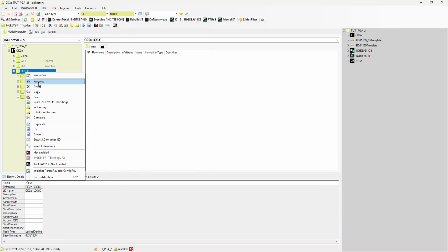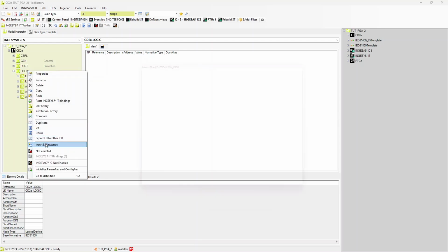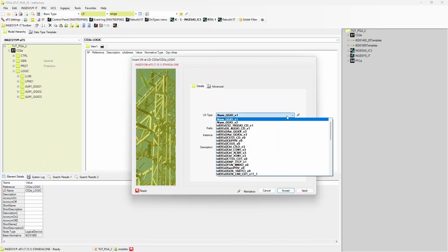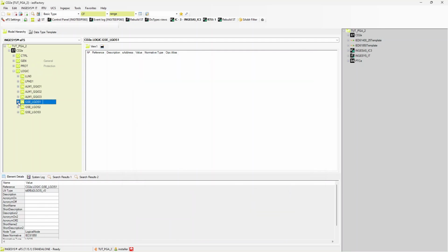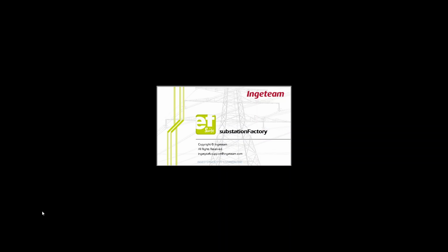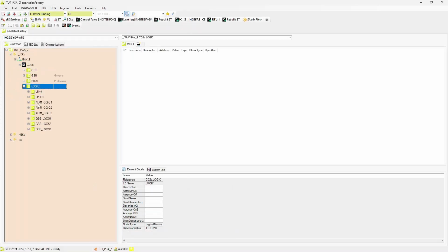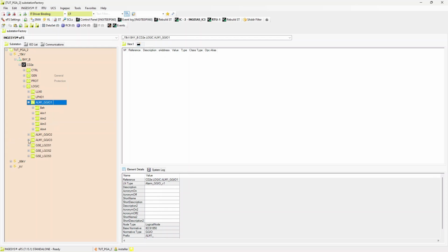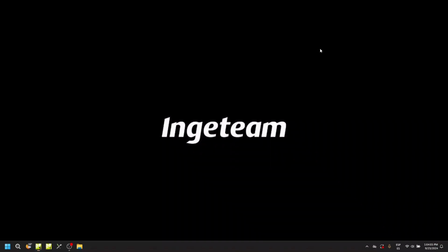Besides homemade logical nodes, predefined logical node types can also be used to further expand the model of each IED. In this case, LGOS GOOSE subscription logical nodes will be included to the logic LD. We can now observe that the modifications made in the EFCD2 IED template ICD have been reflected in the instances the IED has in the Substation Factory installation. Finally, we now know how to modify the IEC 61850 model of an IED with the Energy Factory Suite tool.